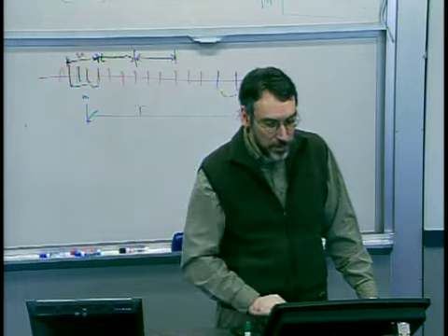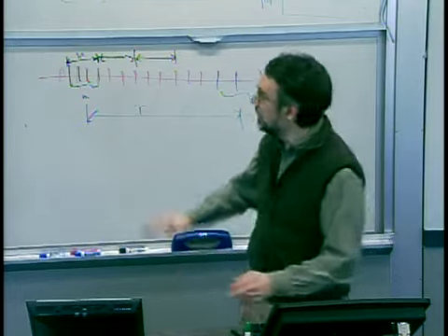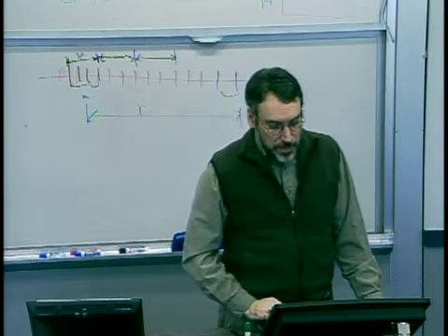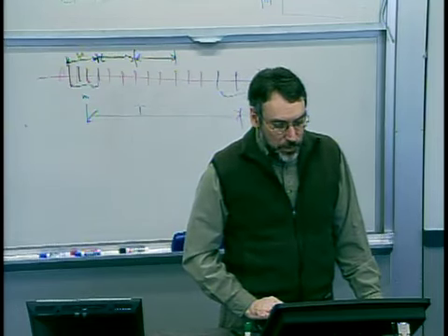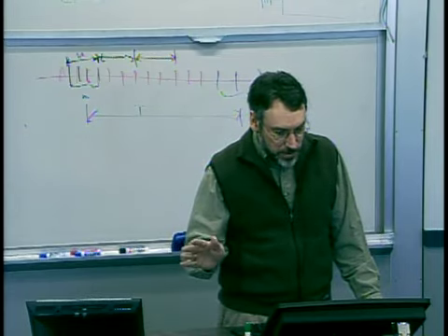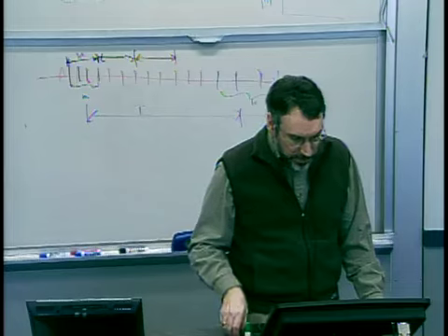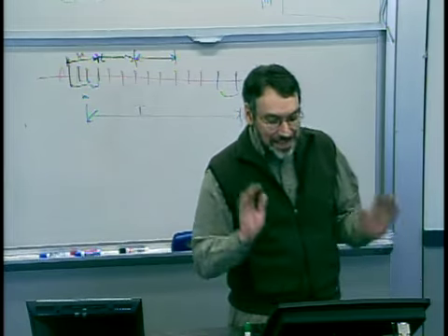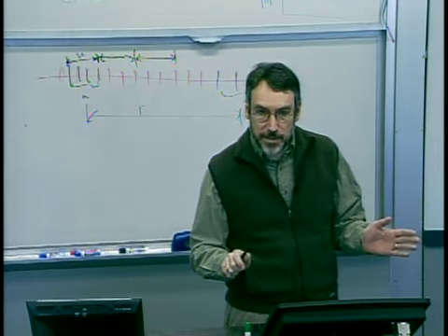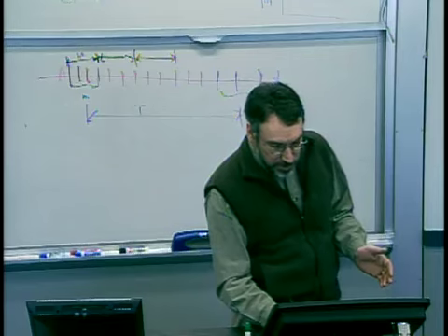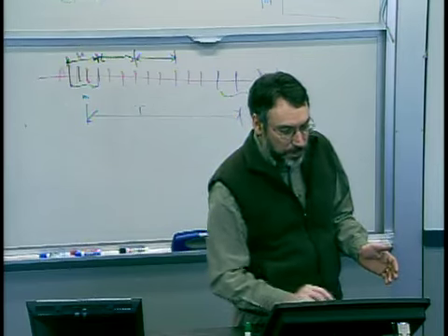So here's an example on the use of tolerances, now pulling in both our distributions and control charts. Here we're assuming the process is normal. What I've done here is drawn, first off, our in control process with its mean and its plus minus 3 sigma points.